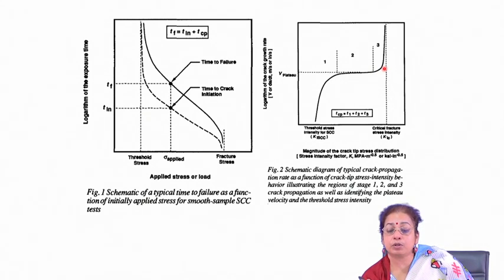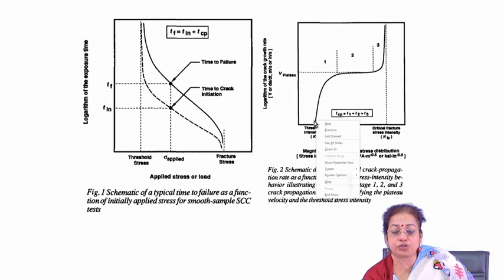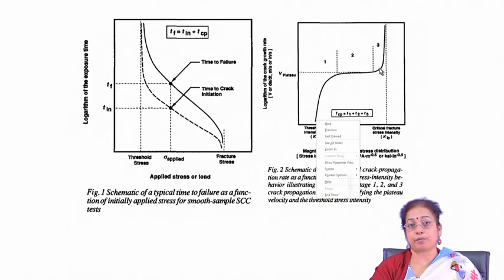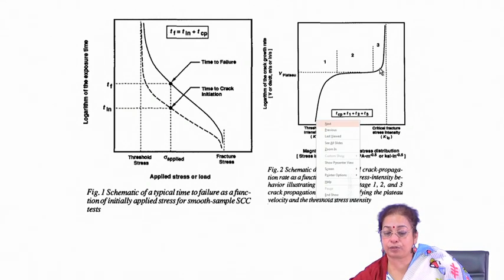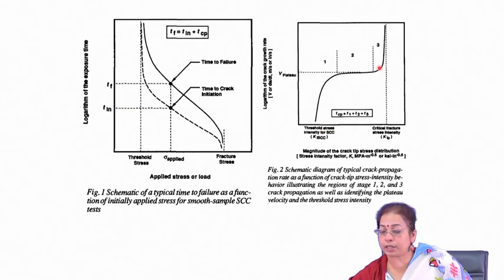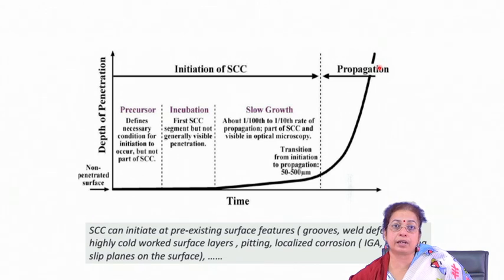In this region, usually the film dissolution rate is much lower. As soon as the threshold stress is reached, dissolution starts, and as you go on increasing the stress or the corrosiveness of the environment, the stress corrosion cracking dissolution rate changes. In the steady region there is dissolution and formation at balanced rates, and after that you will find that the dissolution rate exceeds the rate of film formation. As a result, there is rapid failure of the component. So, it is very important to know the film dissolution rate, or film rupture rate, and also the formation rate under a specific stress condition.